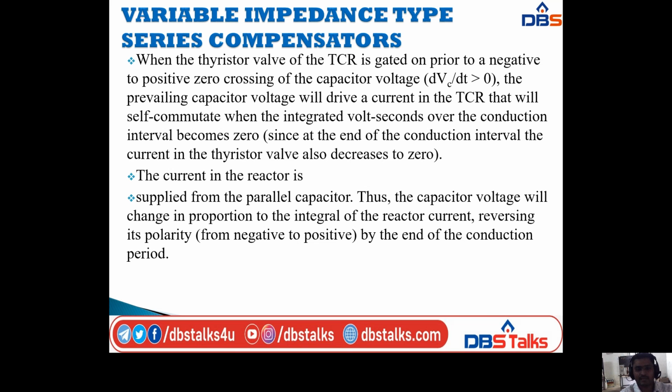at that time the prevailing capacitor voltage will drive a current in the TCR that will self-commutate when the integrated volt seconds over the conduction interval becomes 0. Then the current in the reactor is supplied from the parallel capacitor. Thus the capacitor voltage will change in proportion to the integral of the reactor current, reversing its polarity by the end of the conduction period.